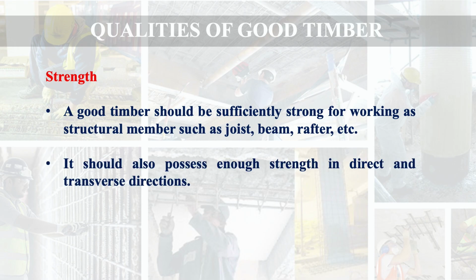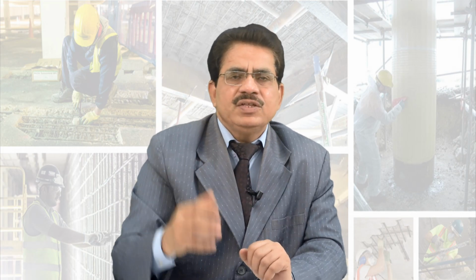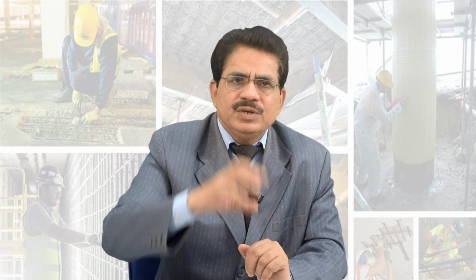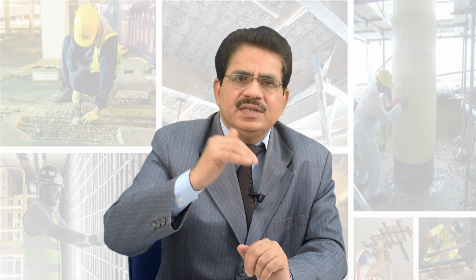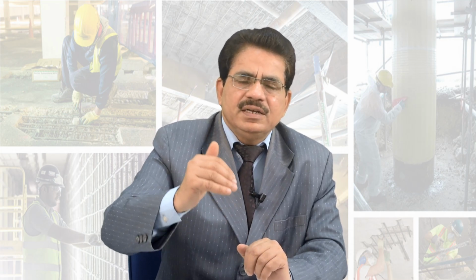It should also possess enough strength in longitudinal direction as well as in transverse direction, because the strength of the timber depends upon the orientation of fibers, and along the fibers and across the fibers the strength is different. So a good piece of timber must have good strength in longitudinal direction as well as in the transverse direction.